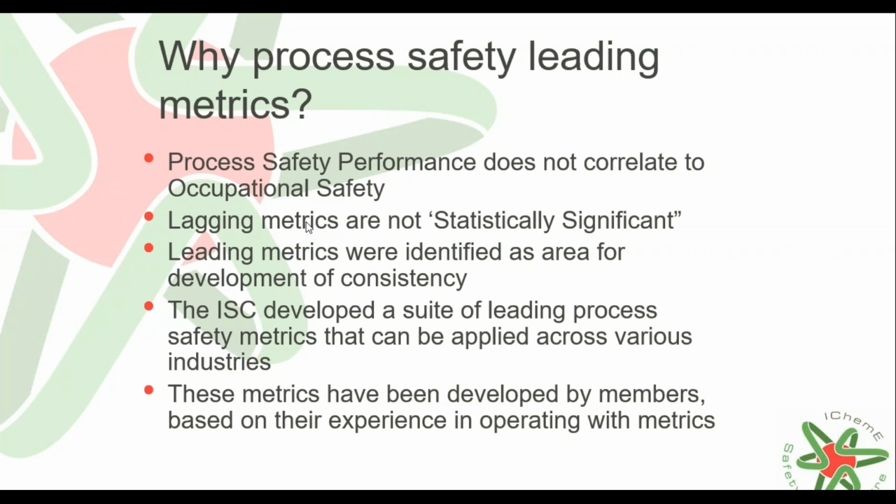You typically start at 1 year, and then depending on the performance of the PSVs individually, depends on the ability to extend that out. So from my experience, I've been in situations where I might have 95% of my PSVs on a 4 or 5 year program, and I might have 5% on a 1 or 2 year program because they're not performing as well. So typically, if the PSV is not performing, it means there's a problem. It means that there's an issue with either the cleanliness of the service, so you need to look at things like barrier fluids. It might be that you're actually exposing that particular PSV to excursions that it shouldn't be seeing, which is causing it to wear out.